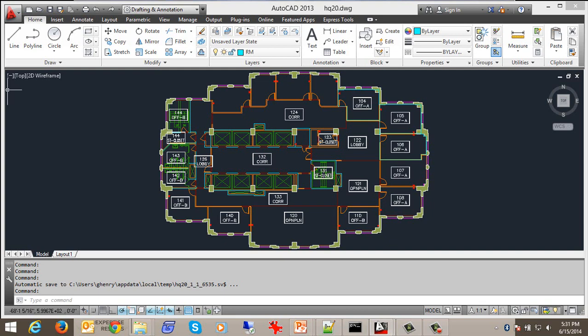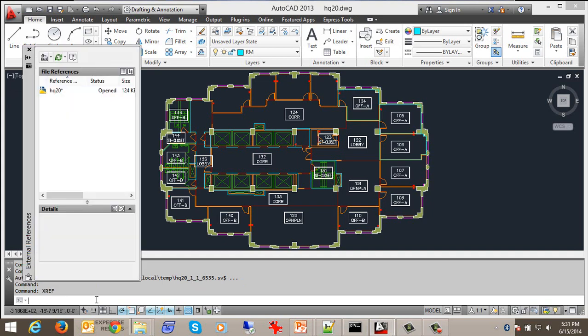The second point we were looking at was the XREF concepts. In case you're not familiar with XREFs, essentially you can open the XREF window in order to work with them by typing XREF onto the command line, and then it pops your window up. Inside of here, you can start dealing with your different breakout of your XREFs.